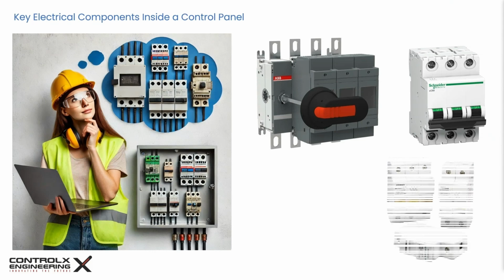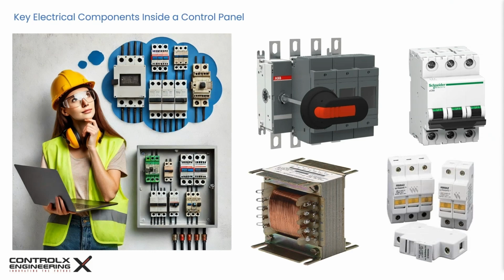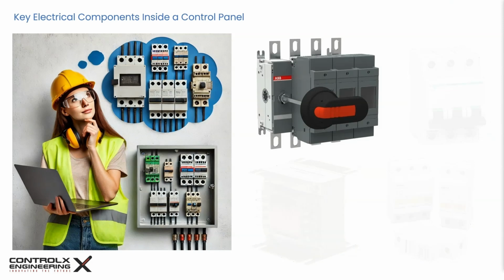Every industrial control panel is built with several key electrical components that ensure safety, functionality, and power distribution. Let's break them down. Disconnect switches. These are the first line of safety, allowing you to completely isolate power from the panel when performing maintenance. But how do you size a disconnect? It has to be rated for the full load current of your system, plus any additional safety factors.